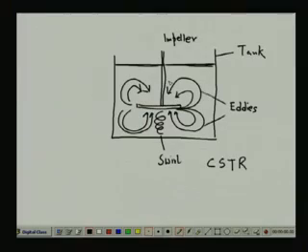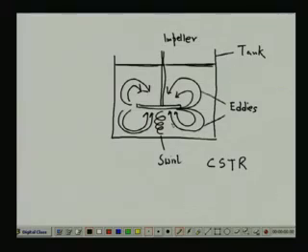This is the basic principle of the bioreactor, because the cells which grow inside the reactor depend on the oxygen concentration. It does not end here, because the dissolved oxygen concentration is a very vital parameter in any bioreactor. If I continuously measure the dissolved oxygen concentration, in the initial stage there will be a good consumption of dissolved oxygen.